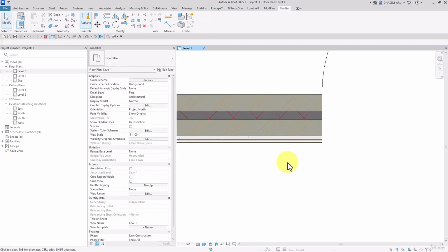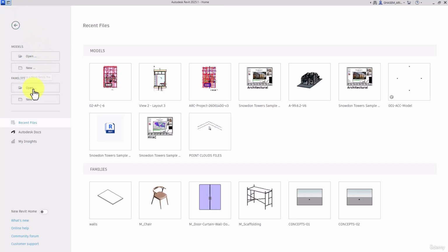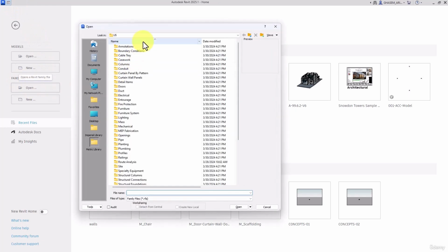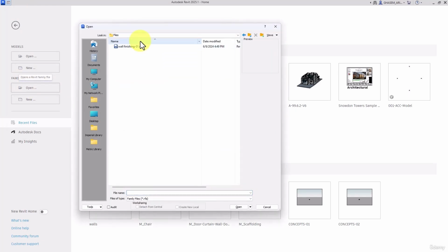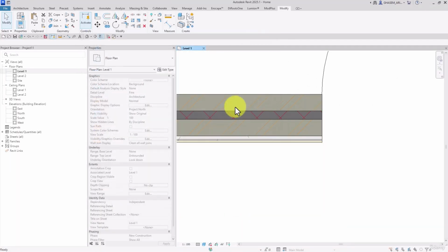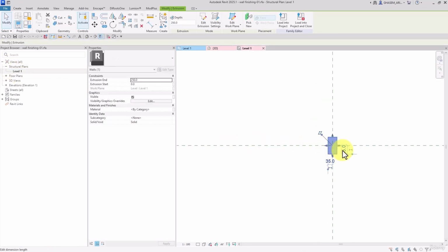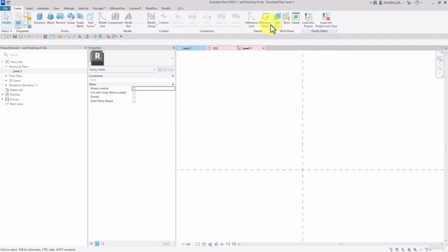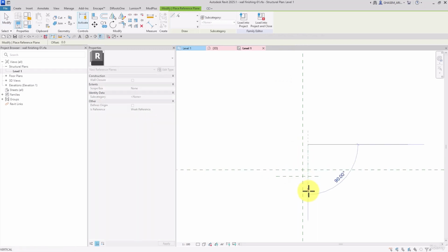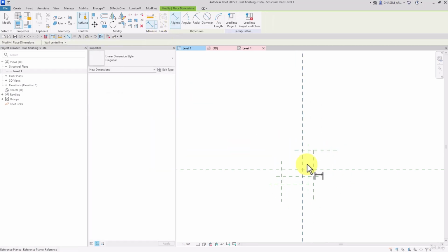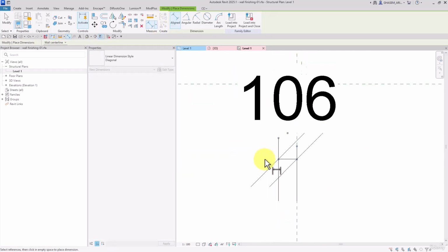Right now, watch this. It was wall and then we exported as family. And right now if I open family, then I open the same file location that we just saved. Check it out. We got a wall family. The category is wall. And this is great. If I delete this afterwards, I can model whatever I want. I can edit the file and create the customized family.